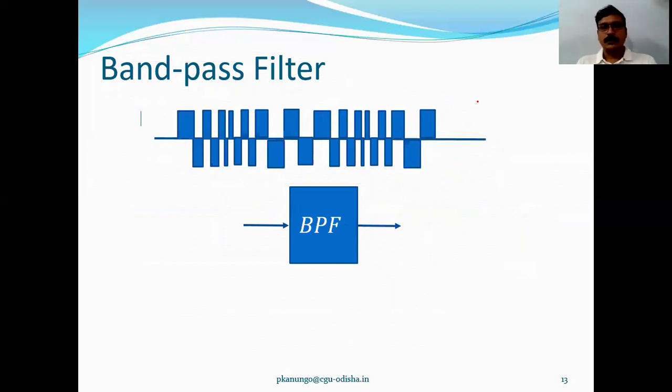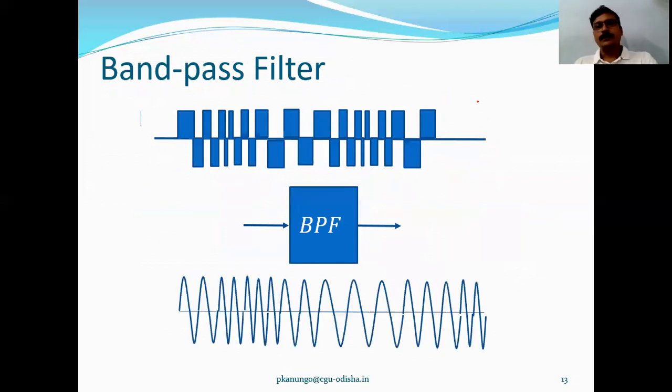Here we are choosing the frequency of this band pass filter as the IF frequency, so that it will pick up the IF frequency component, which is also a purely sinusoidal signal. So the output we will get is an FM signal with IF carrier frequency, or you can say an IF carrier modulated FM signal, but the amplitude will remain constant because of the hard limiter used at the detector.